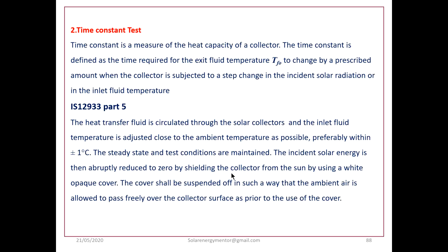What is the collector taking as input? It is taking fluid as input, and it is taking radiation intensity as input. If either the collector fluid inlet temperature or the radiation intensity is changed, the time in which it responds is what the time constant describes. So that capacity is described by the time constant.